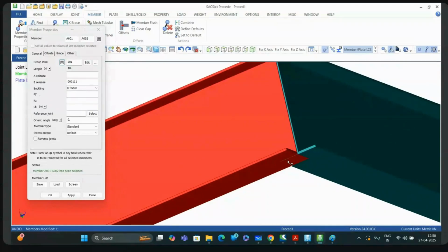But in some cases, the UC values, the utility ratios, will be very high. At that time, we may need to go for these modifications. So this is how we will be doing. We can change the length, we can modify the joints and make it better. Are you guys clear with that? Yes, sir.